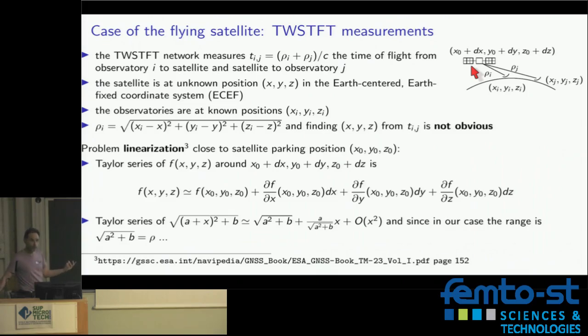And that's actually what I'm doing, because the next item here will be, I want to do passive measurement, and if I'm doing passive measurement, I'm not actively probing the satellite, and I will need a way to subtract the satellite position. Remember, the satellite is moving by something like 30 kilometers around its equilibrium point. And electromagnetic wave propagate at 300 meters per microsecond. So 30 kilometers is 100 microseconds. So if you're not careful, your satellite is introducing plus or minus 100 microseconds in your time transfer.